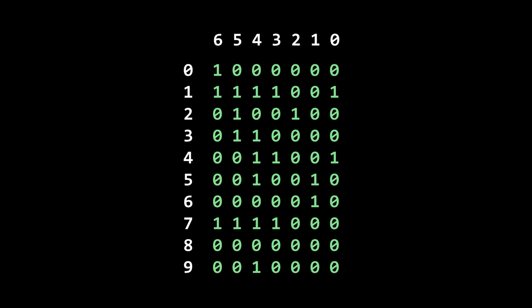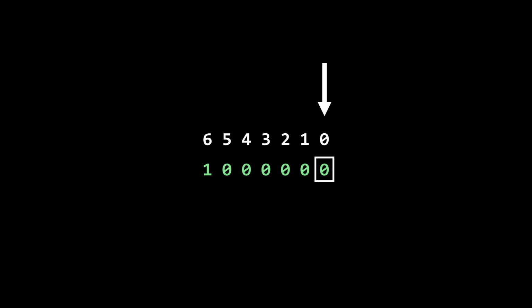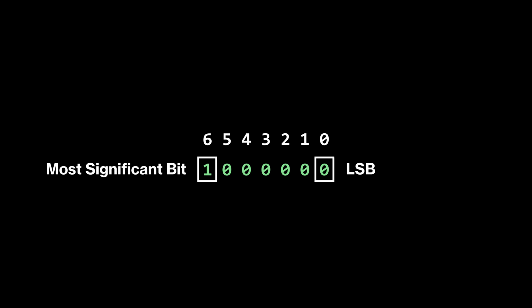A common pattern for multidimensional arrays is to have the outer arrays using ascending indices to track element positions, while the inner standard logic vector uses down to notation to track the orientation of the bits. Using down to means our rightmost bit is the least significant bit, whereas the leftmost bit is our most significant bit, which mirrors how we read decimal numbers and feels more intuitive.